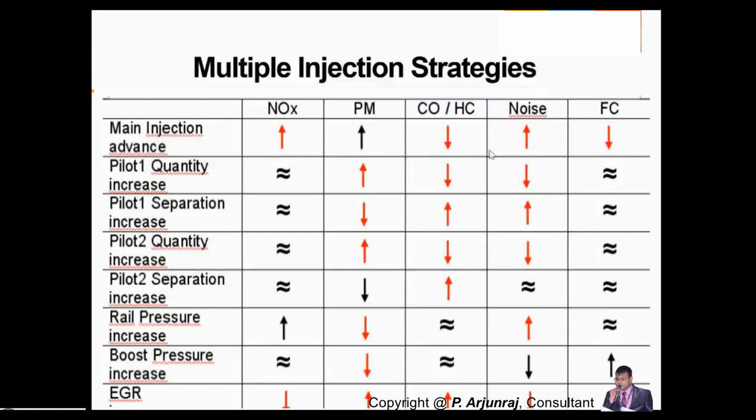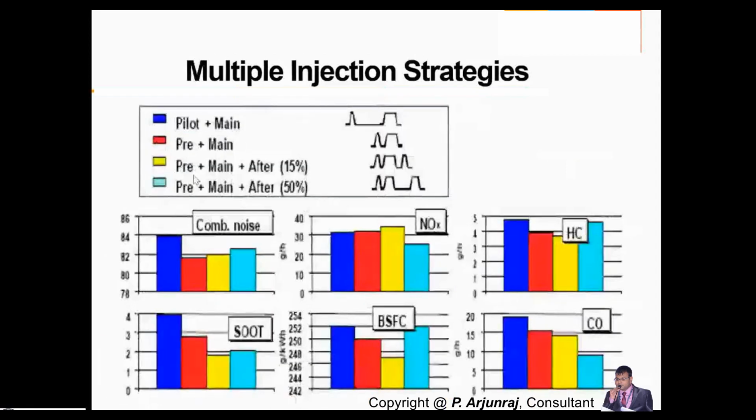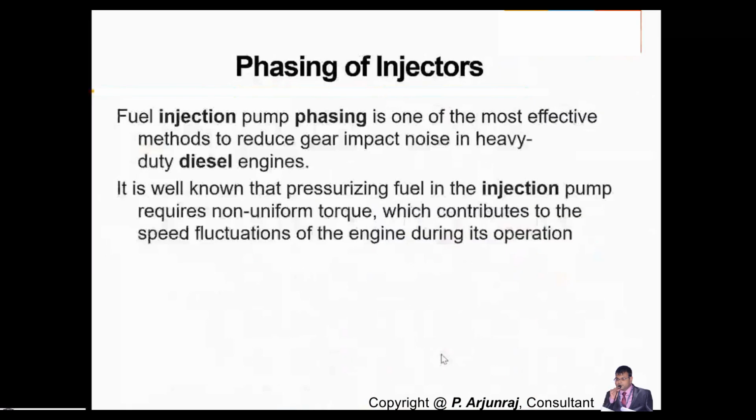And obviously you get carbon monoxide and less hydrocarbon, NOx is also going to be higher, and the fuel consumption is going to be lesser. So when one parameter increases, the other decreases. We have also seen exhaust gas recirculation, which reduces the NOx. When you go for EGR with SCR, by this strategy we can also adjust it. Even with different formulas and strategies, we can play with different combinations, so we need to get the most effective one for our system.